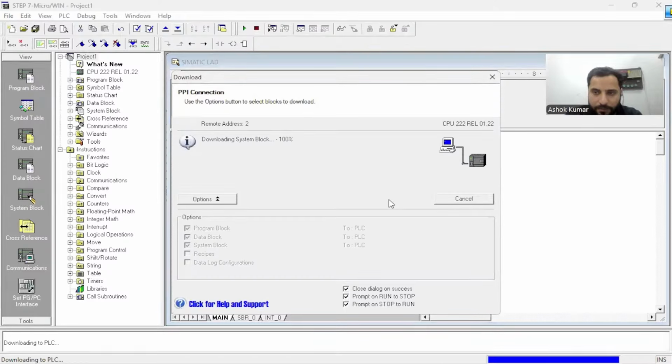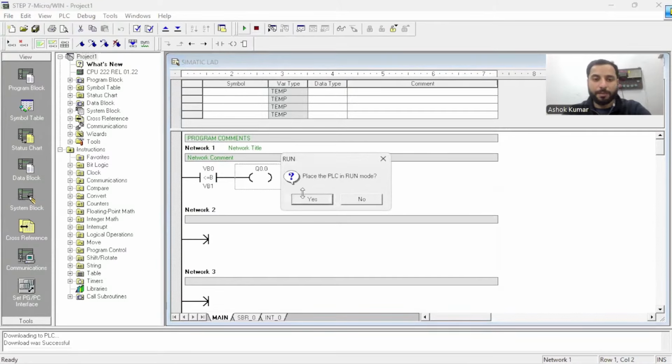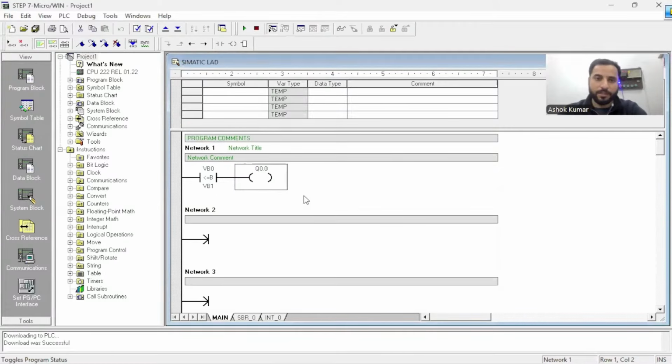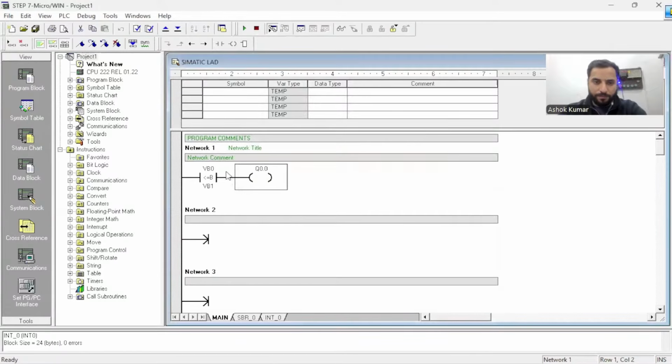I already mentioned N7 colon 0 to 100 in Allen Bradley. Here we have registers according to the blocks. For the byte, we have VB0 to VB100. V means variable, B means byte, variable byte registers. So how can we assign the value in the run mode only?